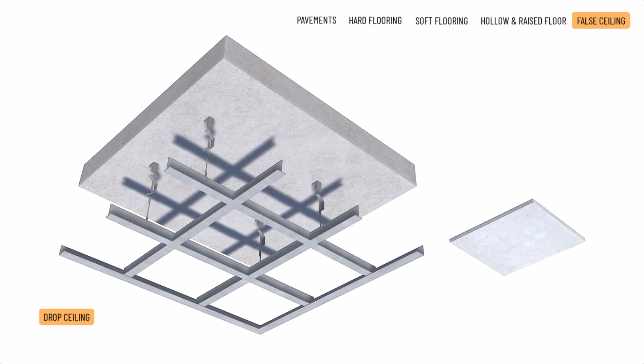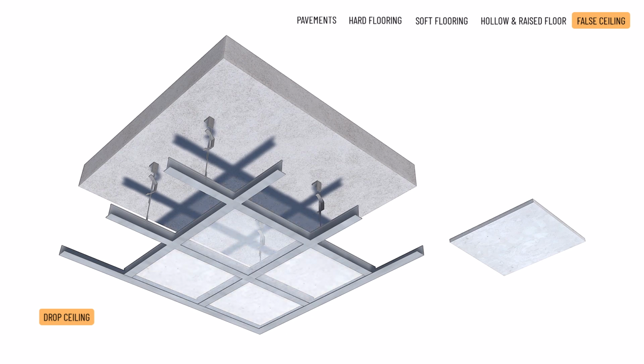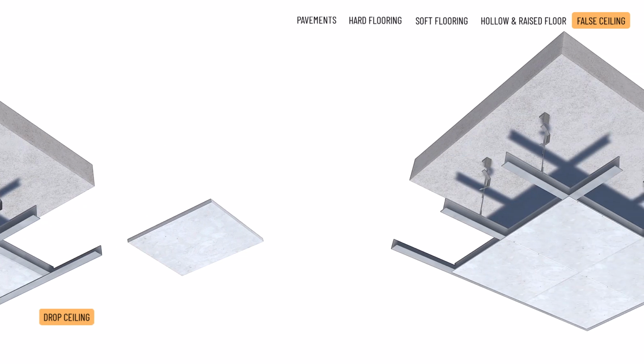Another frequently used technology is the ceiling tile system, where the cladding surface is created from square-shaped ceiling boards inserted between T or Z profile T-bars, typically arranged in a 60 centimetre grid. The grid may be designed with exposed or concealed T-bars. In both cases, the ceiling can be constructed so that it is fully dismountable.